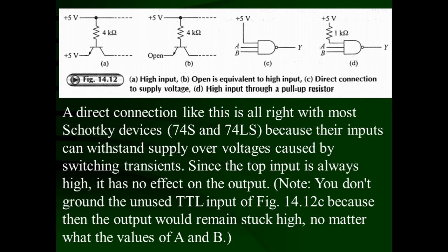But for this transient voltage, there is a built-in protection for Schottky and low power Schottky TTL, and hence we don't require pull-up resistance for 74S as well as 74LS series. They can be connected unused input directly to the VCC.